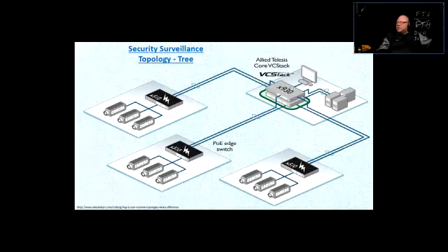Here is the main panel, the main NVR. And let's say one of the points here is connected right to the switch, and the switch also has cameras connected to it. The reason could be that these cameras could be far away from this, more than 300 feet, and as we know, the Ethernet cable is not able to go any further than 300 feet.